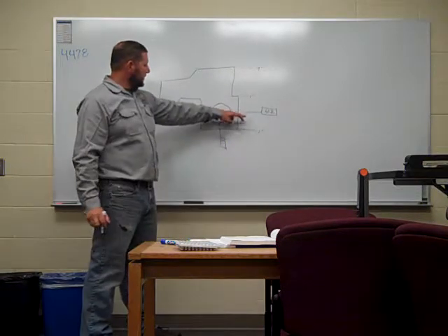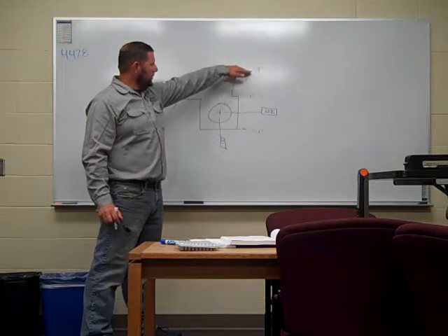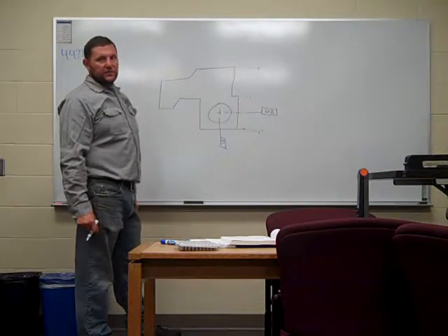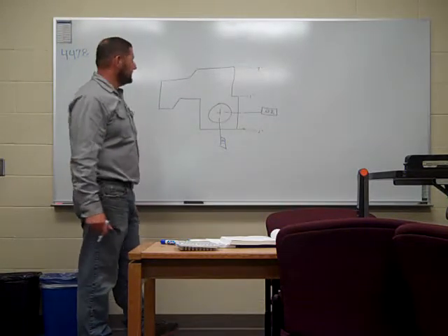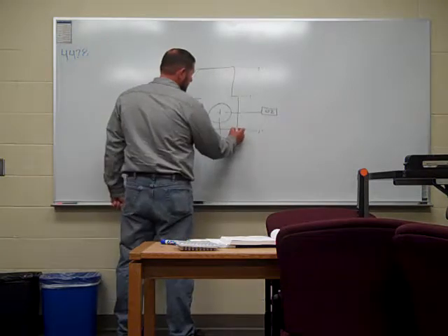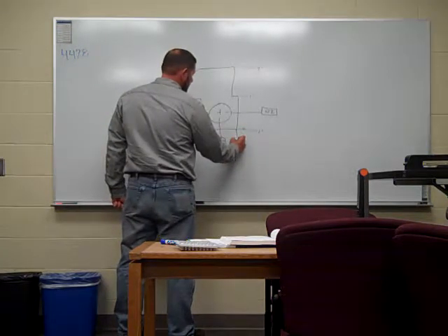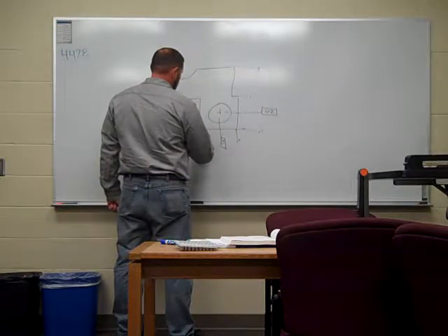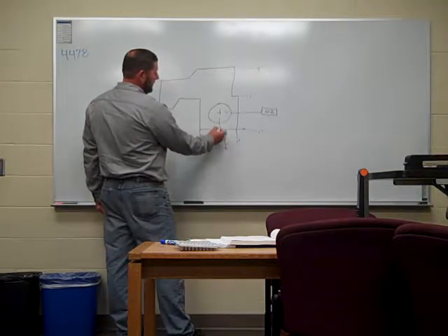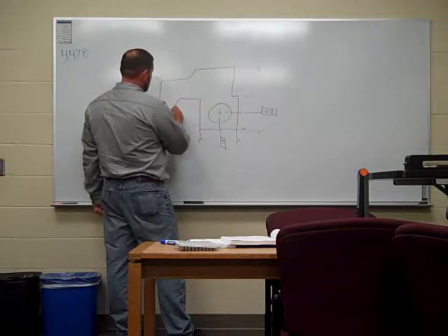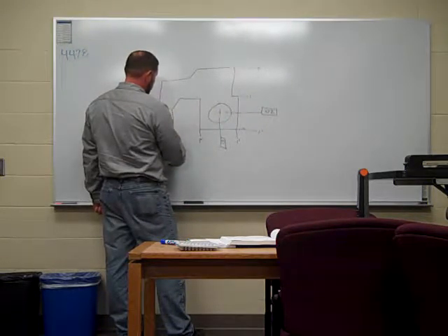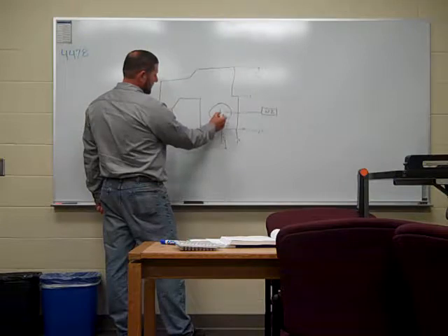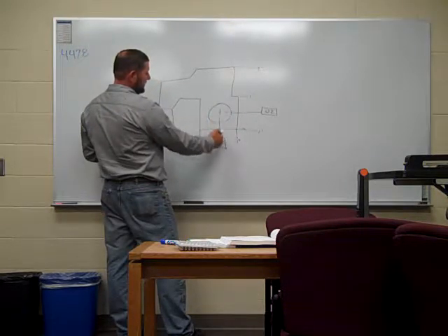So that 4 inches is from the center point of that circle up. No dimension lines, they just use extension lines. It gives you the direct dimension. Same here. So they could have 1 inch here, 1 inch here. So these dimensions are coming off of this 0 plane. So this could be 3 inches. Everything they're coming off of is at the 0 plane.